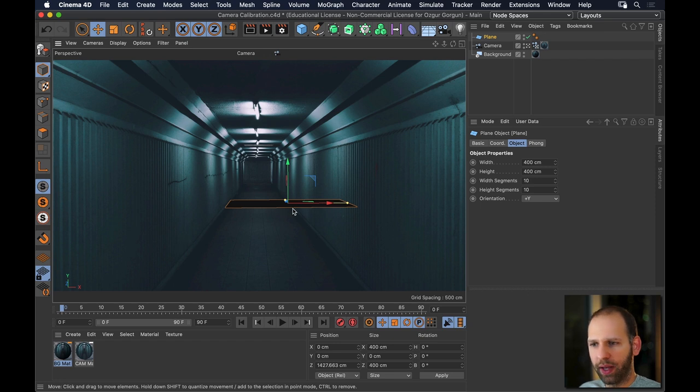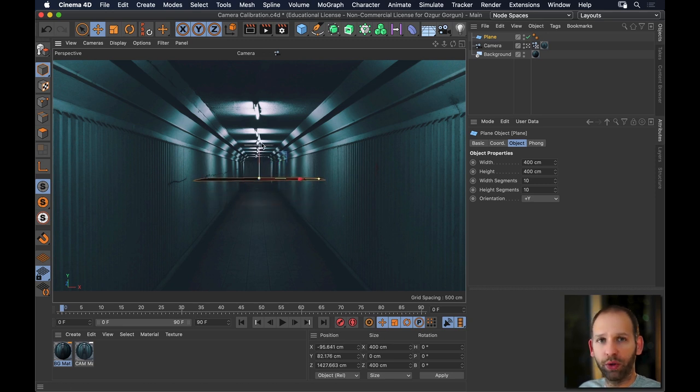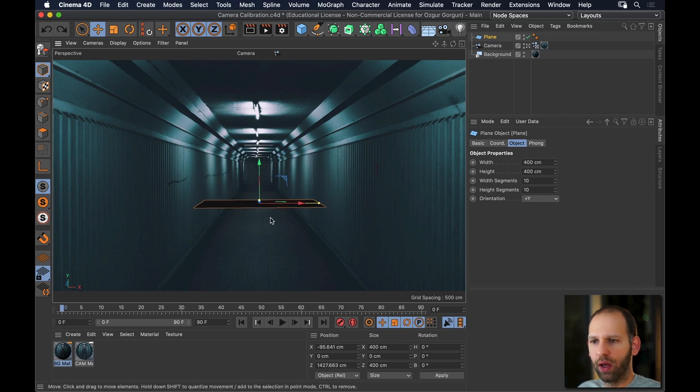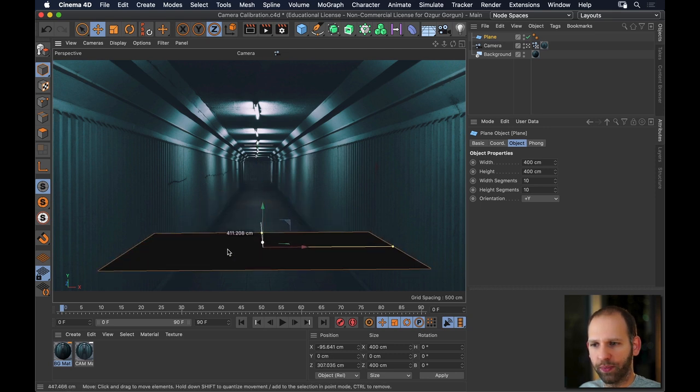Now, I have this plane. What I'm going to need to do is to go and set the plane up to be the floor, so from that, we can start building up the rest of the room. So I'm just going to go and push this here. And I'm being careful not to move this up and down, because then it won't be on the floor level anymore. And if I now want to move this backwards and forwards, you see I can't quite click on this blue arrow here because the other two arrows are getting in the way. But what I can do is to go and turn off the X and the Y here. So when I click on the object and drag, it's actually moving it on the Z. Although I'm not clicking on the arrow, I'm still moving it on the Z.